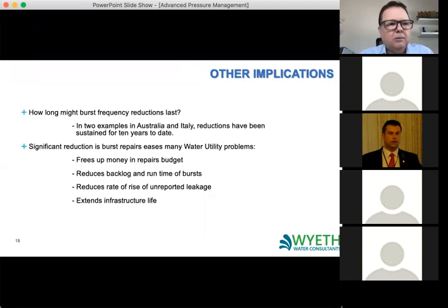How long do these burst frequencies last? Well, there have been cases where it's been more than 10 years. So you put in pressure management, you reduce that burst frequency down. And as I showed you, the strength of the pipe, over time, is going to get weaker and weaker again, but it may be 10 or 20 years before you start to experience more frequent bursting again.